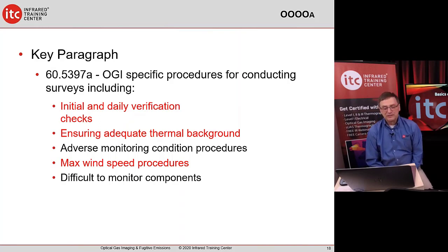Also, you should note that there are some adverse monitoring conditions. If you're in an area that's subject to a lot of wind, a lot of dust, dust floating through the air is going to look very similar to a gas cloud. So it's a matter of, really goes back to training the person's subject matter expertise. And if you have a max wind speed procedure, we did on our FLIR.com/OGI, I'm not sure if that's the current URL for it, but we did have some max wind speed procedures. We were testing leaks, I think up to about 20, 25 miles per hour, somewhere around there. But they had to be fairly significant leaks.